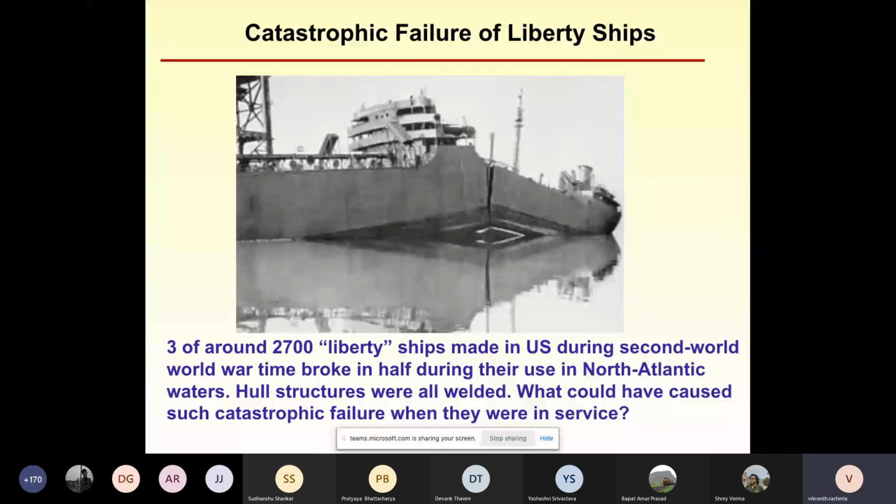Actually, water quenching can be very violent. Water boils at a lower temperature, and because of that, it can lead to very non-uniform cooling, very rapid cooling, which is a problem. On the other hand, if you use oil cooling, it's much more uniform, and the cooling rates are slightly lower, which is good in terms of reducing the thermal stresses.